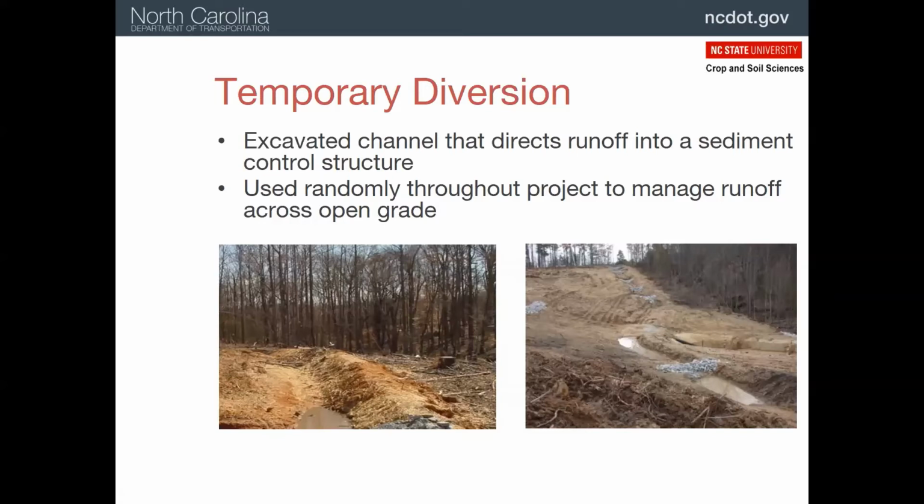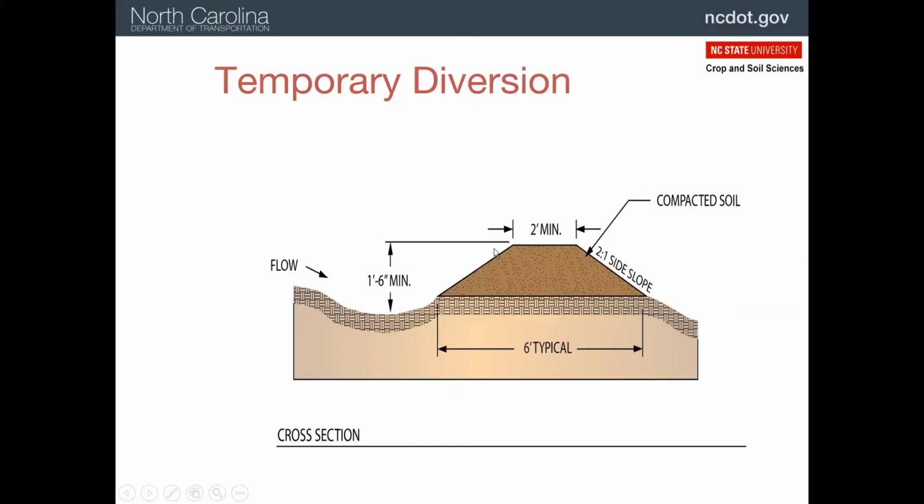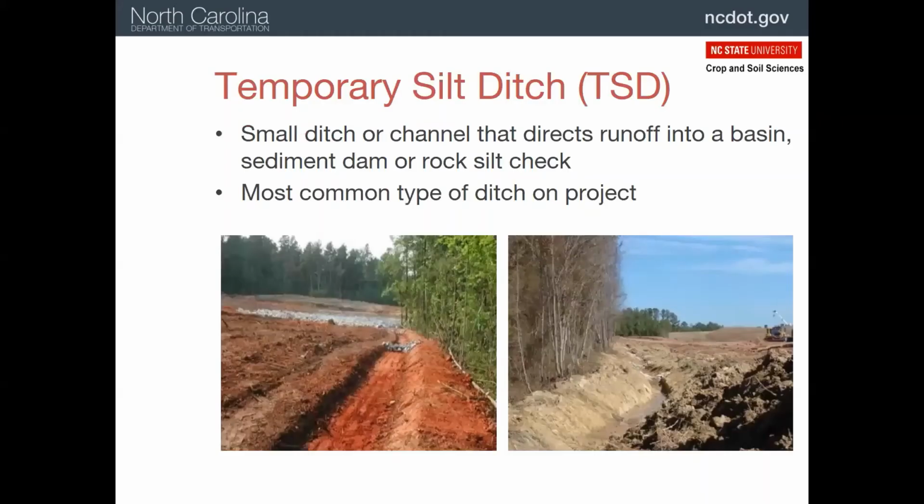So we have a temporary diversion, as you see here, that's catching water before it gets off the project and sends it through a treatment system of some kind. This is the diagram, a pretty simple concept here, and a cutaway where we're cutting here and putting the fill material over here and taking the water somewhere down where it will get treated before it leaves the project.